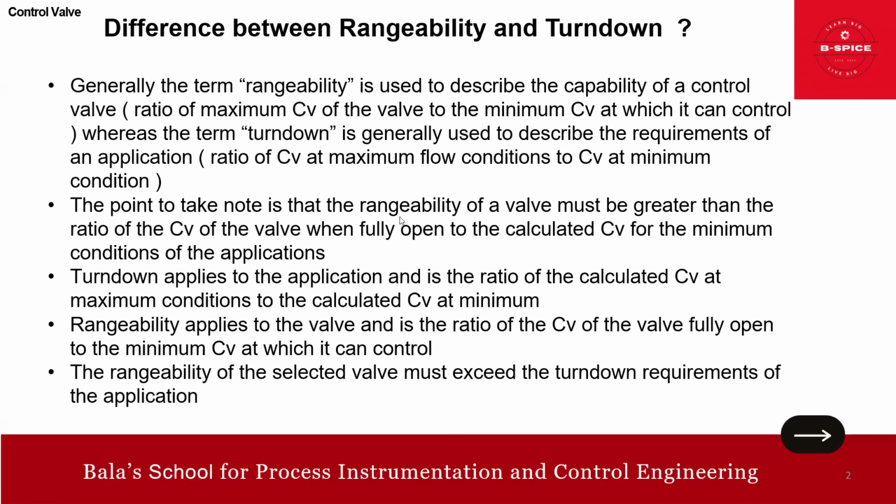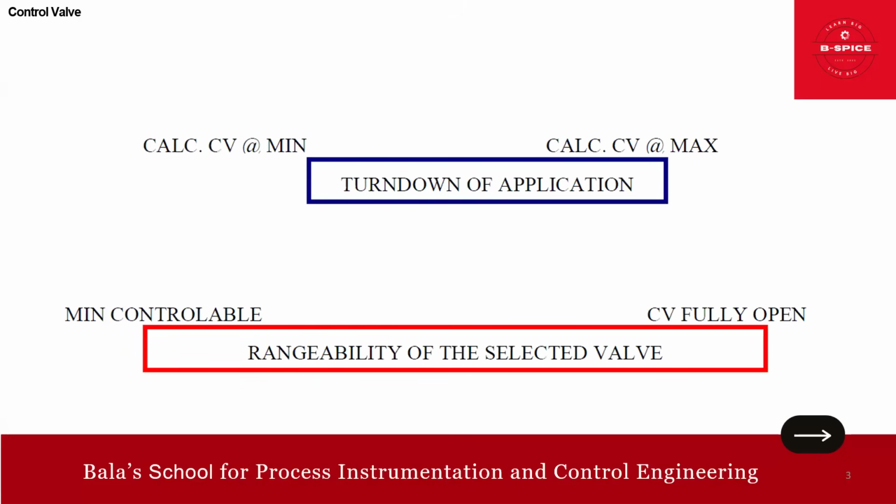So I am supporting this statement. The rangeability of the selected valve must exceed the turn down requirements of the application. You got it? Just always remember, friends, rangeability of the selected valve must exceed the turn down requirements. I'll explain with the help of a picture.